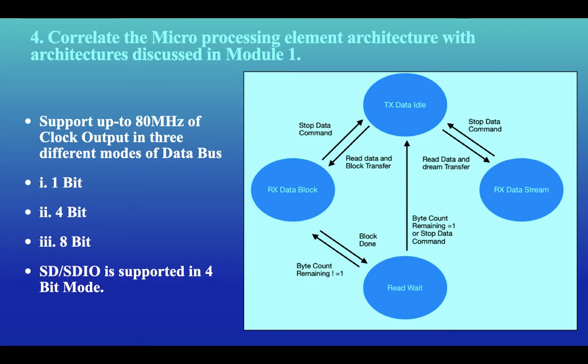The data path loads new data parameters, that is expected data, read or write data transfer, stream or block transfer, block size, byte count, card type, timeout registers, etc. whenever a data transfer command is not in progress. If the data expected bit is set in the command register, the new command is a data transfer command, and the data path starts one of the following operations: transmitting data if the read or write bit is equal to 1, receiving data if the read or write bit is equal to 0. The flowchart for the same explanation is presented here.